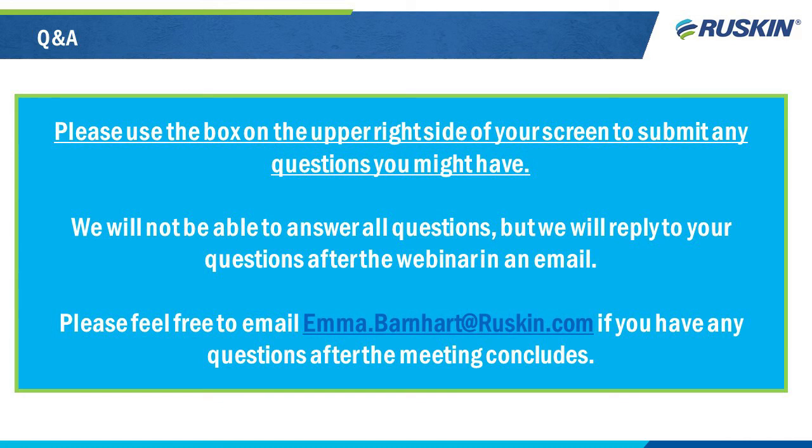Right. All right, thanks. So the next question is, are the actuators typically field installed or factory mounted? Yes, so this question was likely asked early on. In the end, I brought it up here. So actuators can be installed in either setting. They can either be installed at the Ruskin factory or in the field. We recommend that they are installed at the factory.